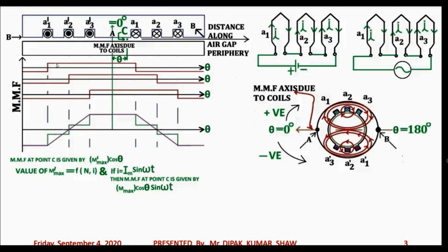Over here in this particular block, this plus ni by 2 and minus ni by 2 will cancel. So you are left with minus ni by 2. In this way, you simply add the MMF in each of the blocks. Block means, I want to say, the slot pitches. This can be more precisely termed as the slot pitch.